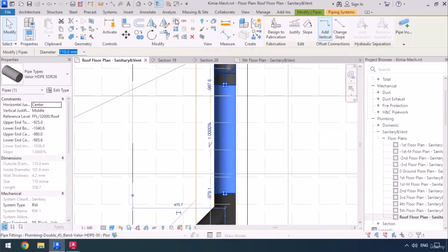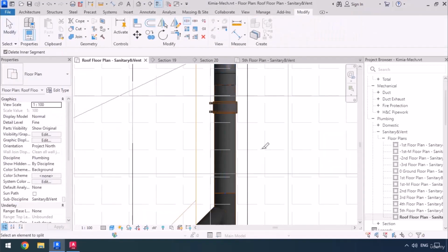Split element, then click here, and now it was able to place that electrofusion family. Now later we're going to have to check to see what the problem was as to why it couldn't place the double flange. We didn't even need one, but we can always go back and see what the problem was. Now another click here, and now you can also see that the segment between the places that we clicked to split has been deleted.